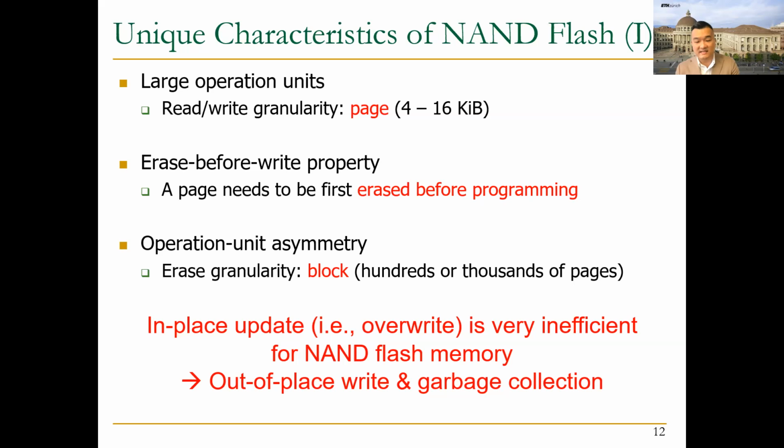So modern SSDs commonly perform out-of-place writes, meaning that they always write new data to a new page that has been previously erased, and perform garbage collection to reclaim the page that stores the old data in order to use the page for future write requests.